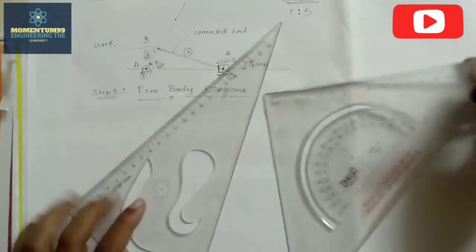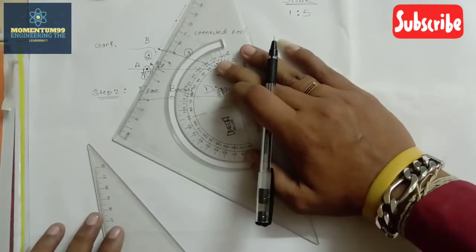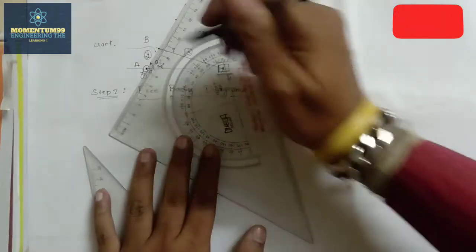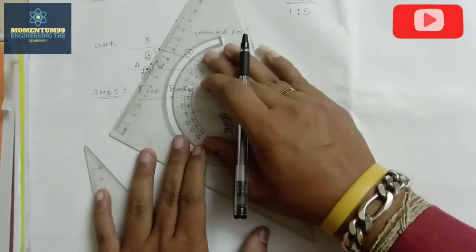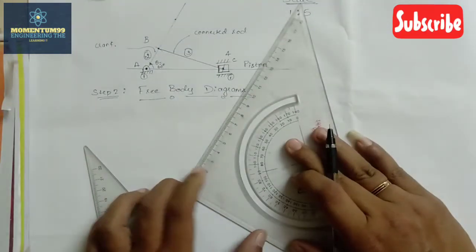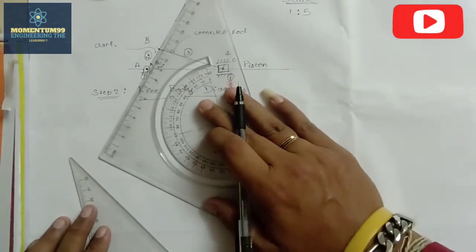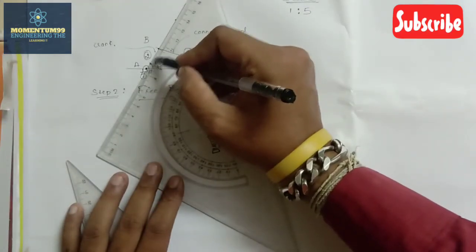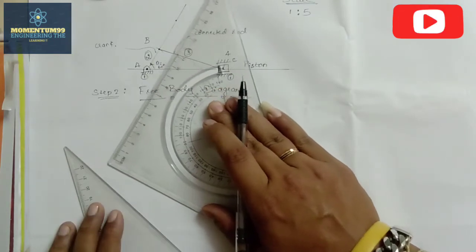Now to draw the parallel line, we should first align our set square with respect to this crank, whatever the inclination of the crank here. Now after aligning, see this edge here; this is the edge we need to reproduce again. This line should be reproduced parallel to the position of AB here. So I will be aligning the edge of the scale with respect to this edge AB, that is nothing but the crank here.